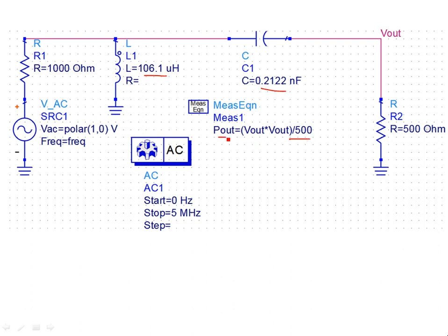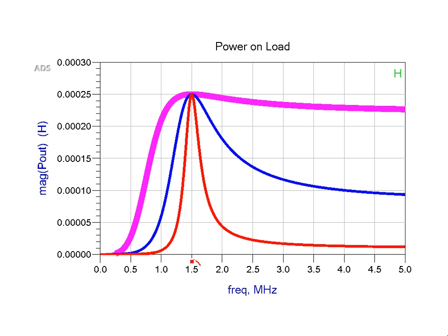So this is again the power P out which is being delivered to the load, and you see at the design frequency, again you have the maximum being transferred to the load at this point. In this region, all three curves agree that the maximum power is transferred. At DC, you have no power transferred in all three cases.